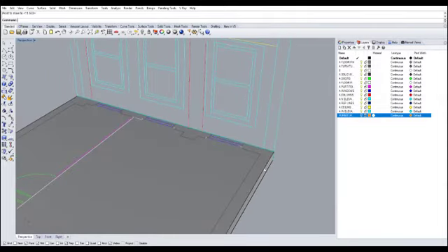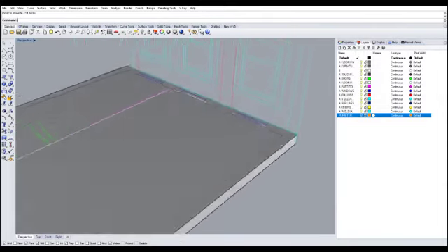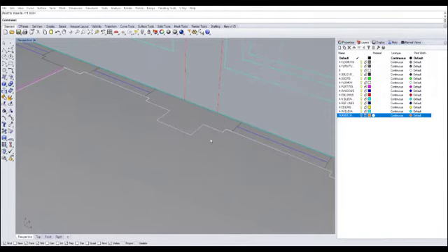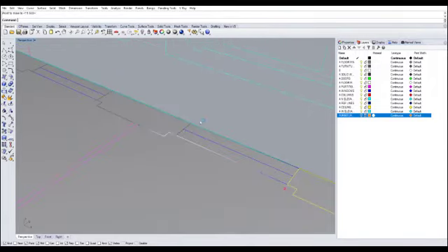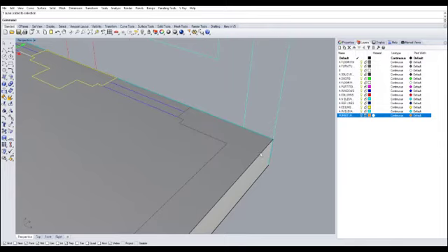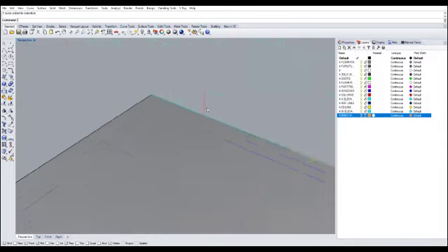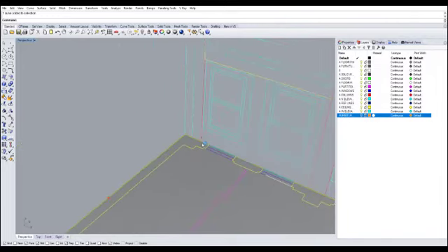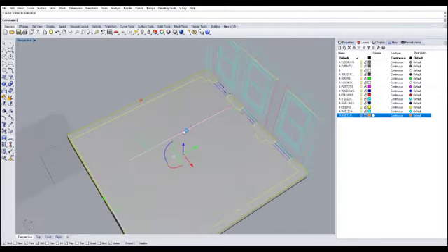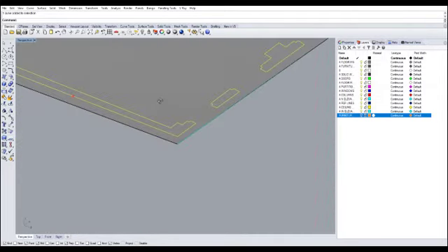Our next step is the wall, which is directly above the floor. Same as we did with the floors, to make it 3D using the extrude command, you first have to select the geometry. If you notice, there are a lot of overlapping lines here, and Rhino allows you to see through the overlapping geometry while giving you a choice of which of the overlapping drawings to select. Now we currently have our wall selected, but we also want to extrude our floor plan.